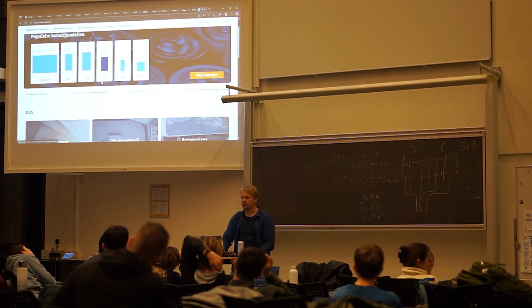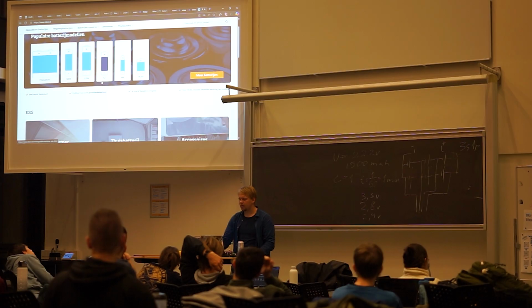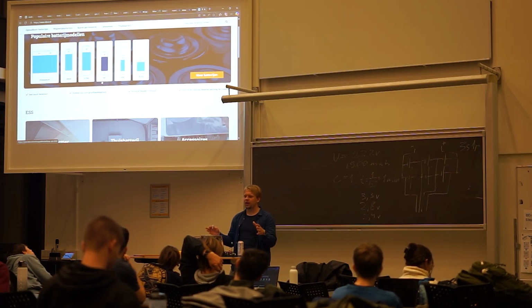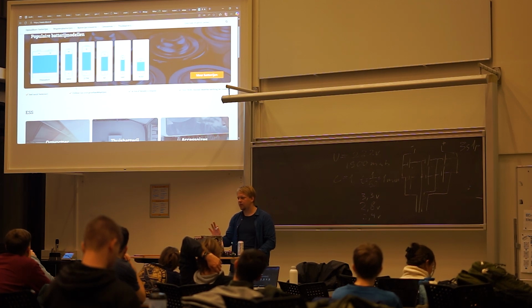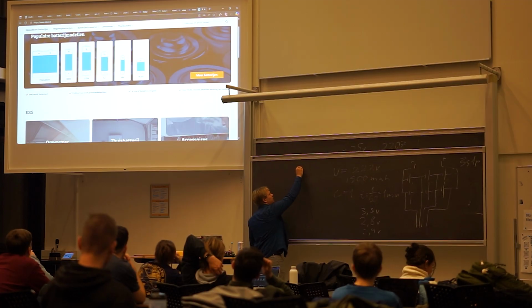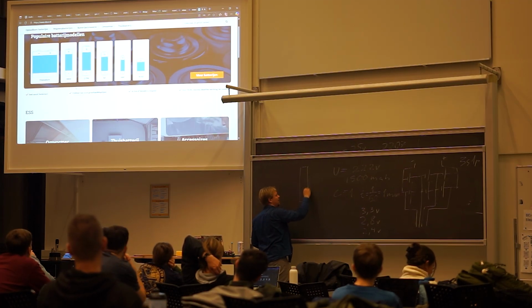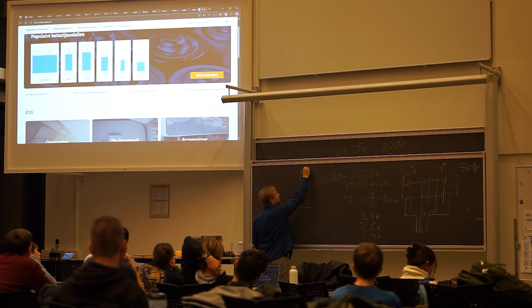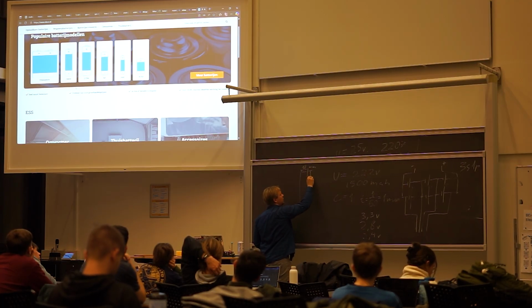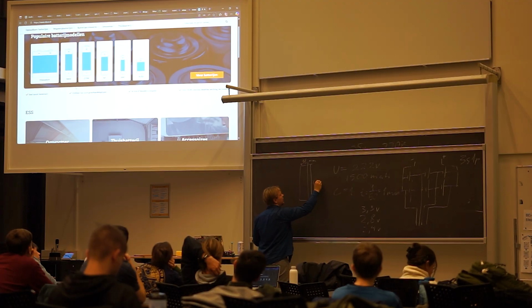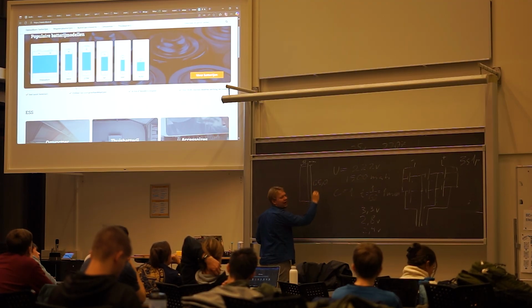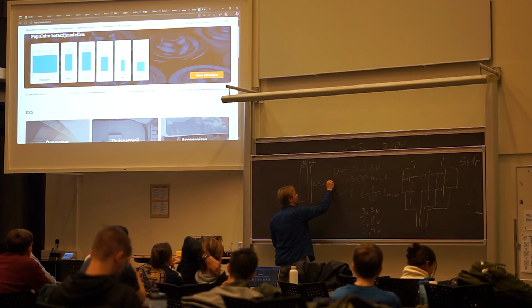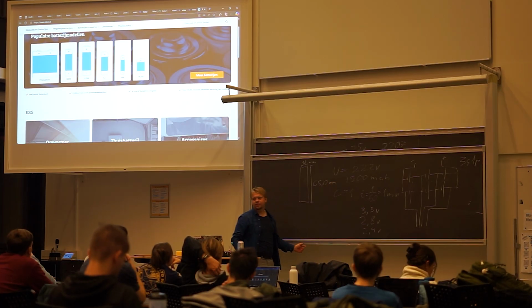Also, because lithium-ions are old, there are usually standards for the sizes of the batteries. The 2 main standards are 18650s. I will explain that quickly. We have a cylinder again. 18 here, and we're in Europe, so it's millimeters, and 650 is decimillimeters, so 65 millimeters.